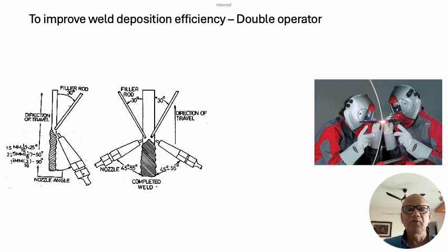Current and voltage can be equal, similar, or also more or less. You can adjust it, but the trick is to not have both the arcs at the same point, but have a little shift. Little shift means literally a 1 to 2 millimeter shift only in the arc from both sides.